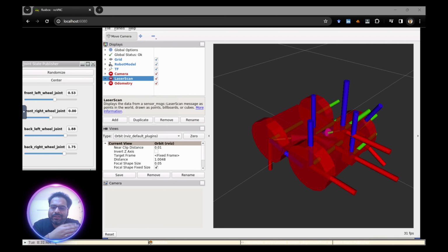The difference between Gazebo and Rviz is that Rviz typically helps you visualize the sensor feed, and Gazebo typically helps you visualize the environment. So for example, if there's an obstacle in front of your robot and you have a laser scanner sensing the distance to it, all of this happens inside Gazebo, and inside Rviz you're going to see some sort of a point cloud. That's basically going to tell you, okay, I see some obstacle, I see some free space.